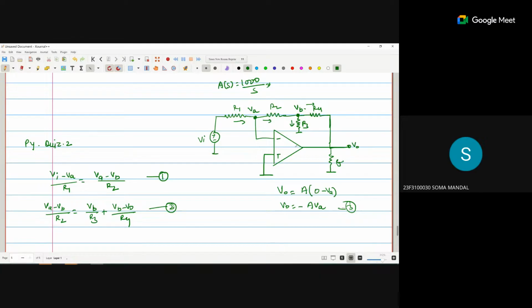Sir, it is given that R1, R2 equal to R, R3, R4 equal to 2R, and R5 equal to 4R, then derive the expression of the transfer function. I can assume R5 is 4R or I can assume R5 is 100R. This is the load resistance, and we already discussed that load resistance never has an effect on the transfer function. Yes, sir. So R5 is only for confusing. Now I got it.